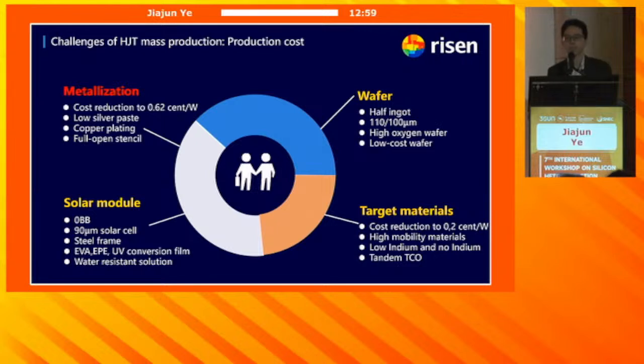But what takes this long to bring heterojunction to the market in commercial supply? The main reason we're thinking is the high cost of production, and among all the costs, the metallization part has the highest share, I believe. In the past years, silver consumption for the metallization for heterojunction was over 20 micrograms. We know that silver is quite expensive, right?